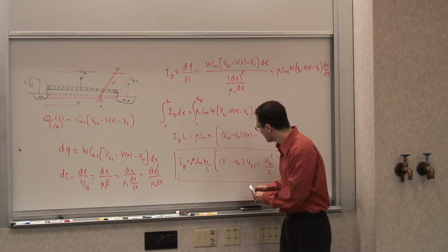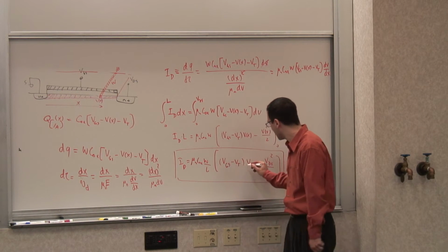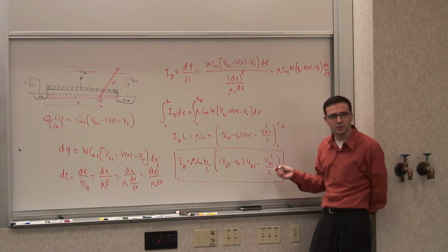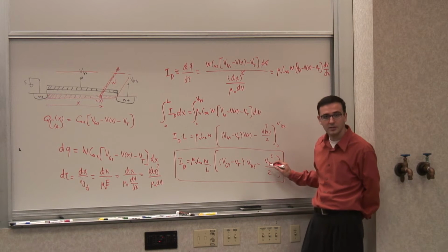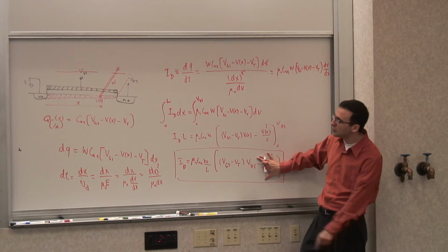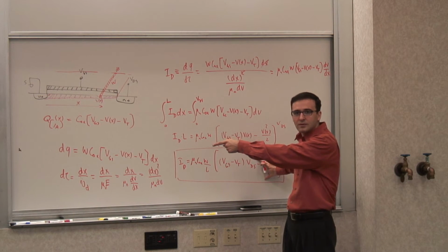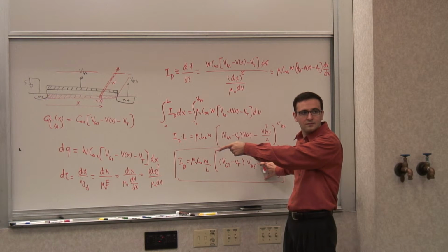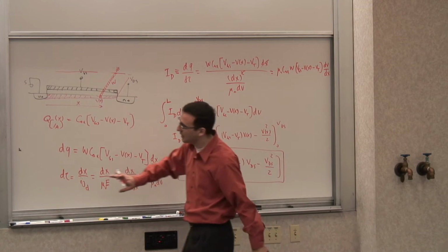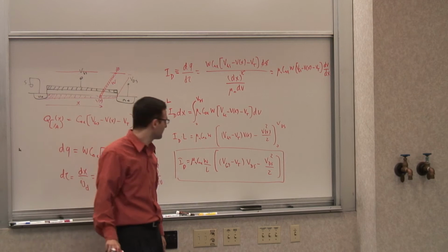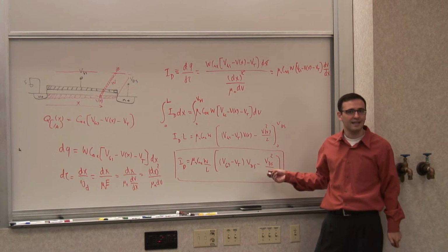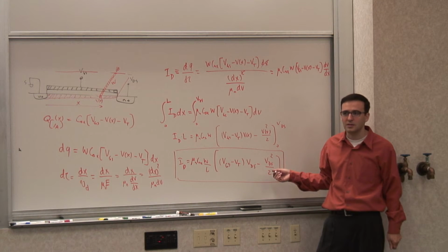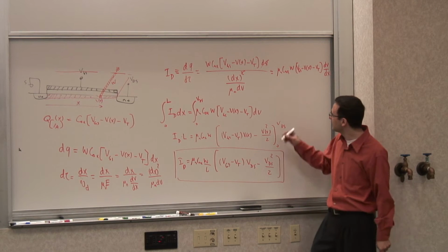Right? So what I have is an expression that relates the drain current to the gate source voltage, the gate voltage that controls the resistance, and to the drain source voltage. Now you can see for small VDSs, this term is not dominant, it's going to be small. So it reduces to the expression we derived, so it becomes linear. Right? We have that relationship. But now, if VDS is large, then there's a second order term, a correction term that makes it nonlinear. So the relationship is not exactly linear anymore. It basically becomes a limiting term.